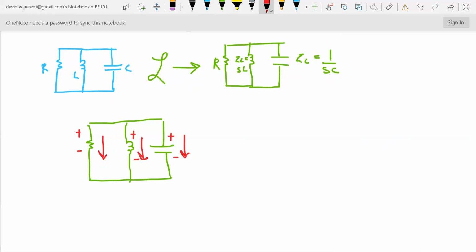All right. So because it's all leaving, right, I can say, and I'm going to use capital for the S domain for the current. All right. So IR plus IL plus IC equals 0. Just to remember, when I'm using the capital, I'm leaving off the fact that it's a function of S, which is a complex quantity that we'll find out later. So there's really just one node. I call it 1. And the reference node, which is ground.